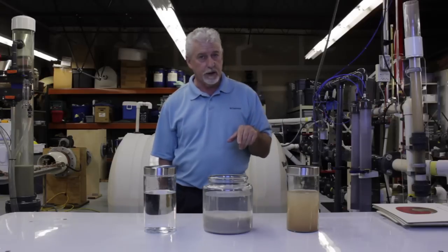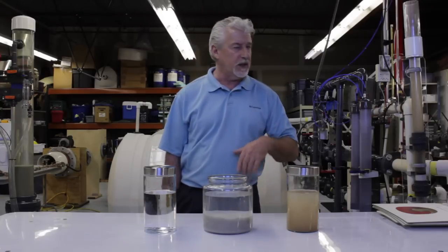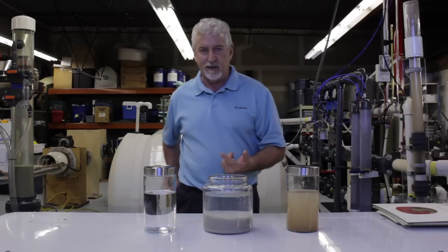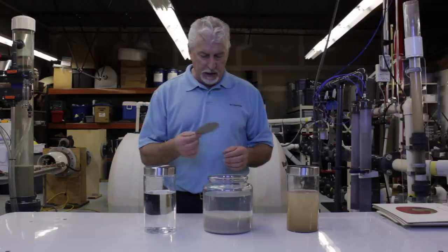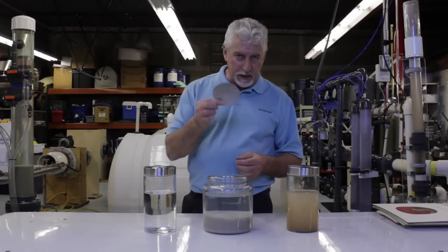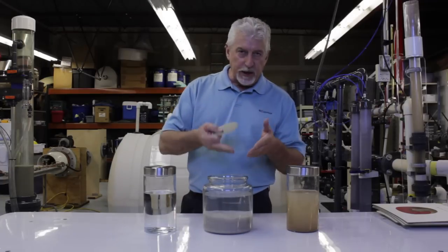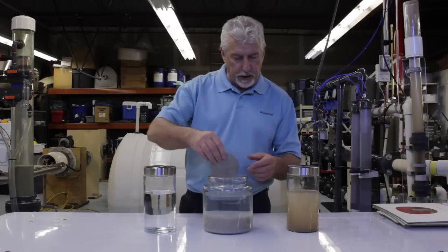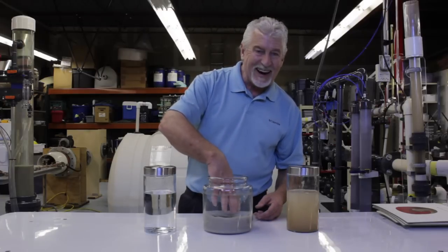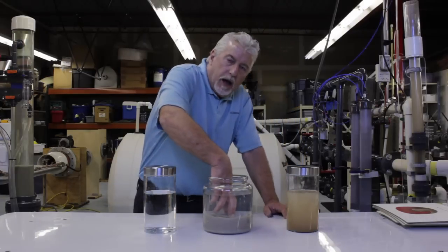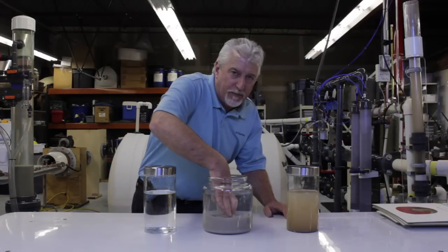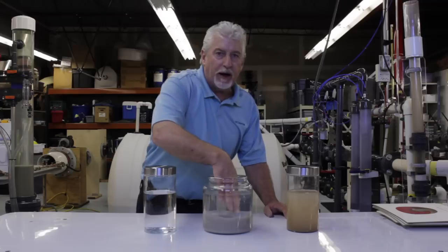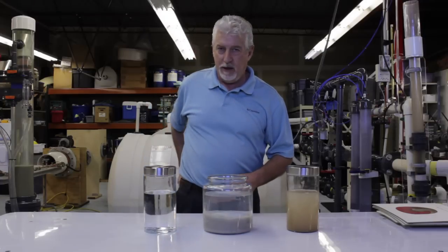Let's first get rid of the shifting problems, the low flow channel, high flow channel, tanks out of level. Let's get rid of that. We're going away from gravity. Let's mechanically compact the media between stainless steel screens. So we'll take our granular filtration media, put it behind a screen and put mechanical force on it and hold it fixed so it can't shift at minimum void, and all our flow related problems just went away.